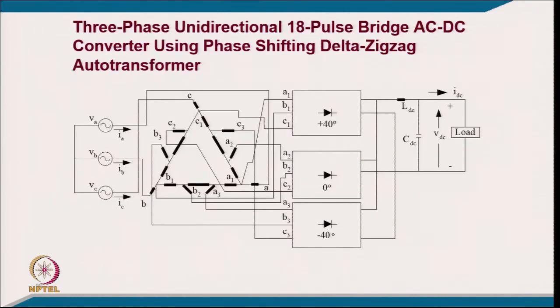Now, coming to another configuration, 18 pulse can be realized another way, by 9 phase, but here the phase shift is 40 degree. 9 phase means 360 by 9, so that requires 40 degree phase shift. So, that is another way that you can have 3 phase conversion into bridge configuration, which requires an odd number of phases, that is either 3 or 9 or 15, and then you can have bridges to convert into an even number of pulses. So, 9 phase also will give 18 pulse.